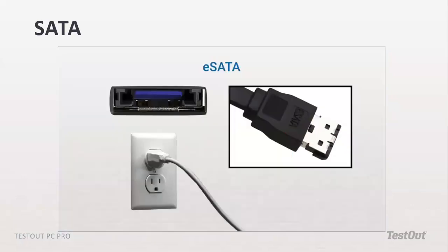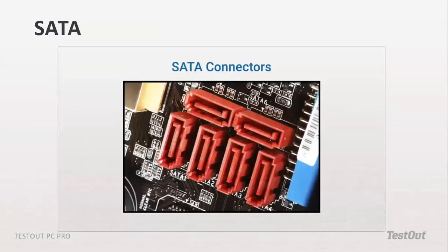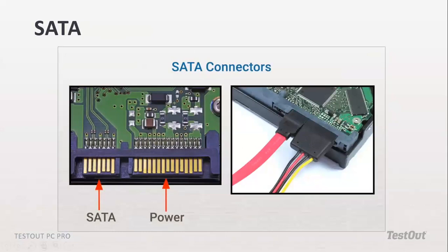So basically that's it. Now, one thing you should also have figured out by now is that the SATA connector only transfers data. It doesn't provide means for us to transfer power. So that lack of power has made it so that inside the drive, you have to connect the SATA cable for data, and then you connect the 15-pin cable for power.